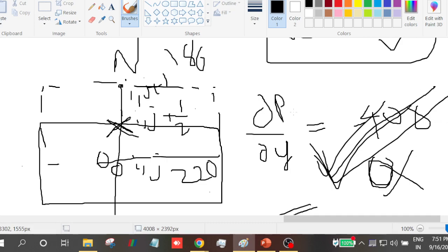So I hope that this gives a clear understanding of why we have to use a staggered grid, because that is the main aspect in CFD according to me. If you don't know why you are using a staggered grid, you will face a lot of issues when you are implementing it. When you understand the background behind using some particular method, then you will be much more confident while using the method.